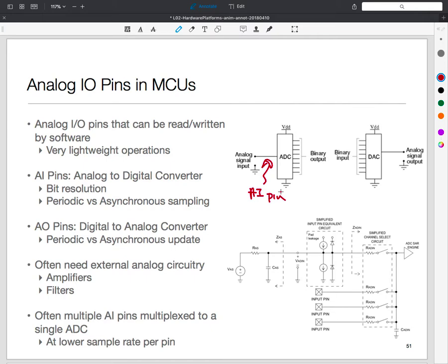Rate is another part. There are phenomena which change very rapidly, and therefore you need to be able to sample them very rapidly. And again, making a fast ADC is pretty hard. So if you need fewer bits and you need to sample slowly, like, I don't know, it's a temperature, it's pretty slow. On the other hand, if it's acceleration of the human body, you need to perhaps monitor it in kilohertz.